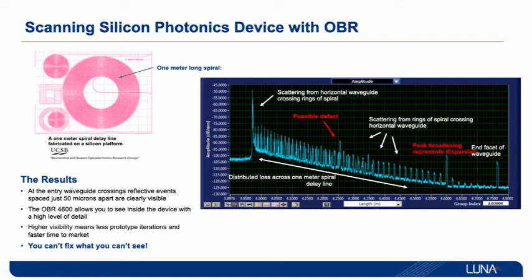If you look at the pink mask layout there, on the right side, you'll see a waveguide trace entering from the right at about the middle, and then it crosses a circle, and then it goes up and to the right, and it goes into a spiral. And the spiral crosses the entry waveguide every revolution until eventually you get to the outside of the spiral, and you can get back off the chip.